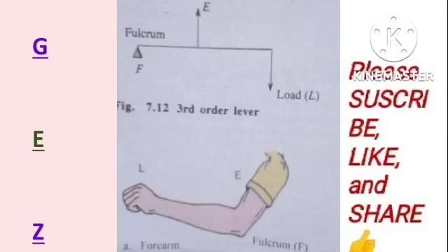The third class of lever, also known as the third order of lever, is a kind of lever in which you have the effort between the load and the fulcrum. Examples of these are forceps, tongs, forearms, and so on. You can see this forearm. In the middle you have your fulcrum, on the right you have your load, and then on the left you have the effort, which is the muscle that moves the lower arm. So this is an example of a third class lever. In this case, the mechanical advantage and velocity ratio are less than 1 in the third class lever.